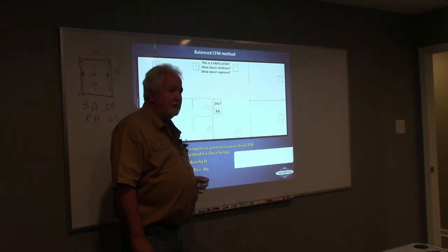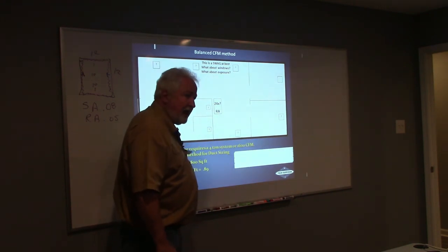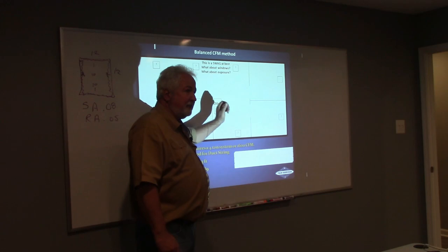Shouldn't I have gone with 24 by 36? 24 by 36, try it. Did I do it? Yeah, 1728. Good, so you see what we're doing there? We're taking a CFM that we have to move, and I have to build a return for that. We're making it happen. Everybody good?